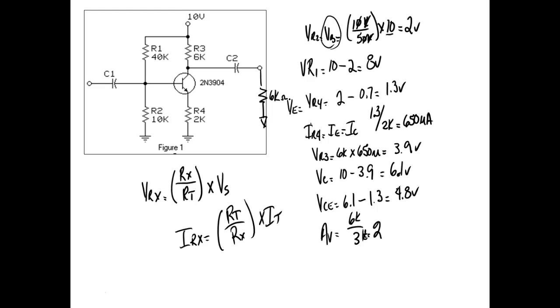So I've got a battery, and I measure that battery unloaded with my meter. And then I come over here and I put a resistor across that battery. What would you expect the voltage on that battery to do? Would the voltage on that battery go up or would the voltage on the battery go down? If you've got your meter out there on your car and you hit that starter on that car, does the voltage on the battery go down or does it go up? If it went up, that would be great. That would say that the battery has absolutely no internal resistance at all. And there is no such thing as a source that has no internal resistance.